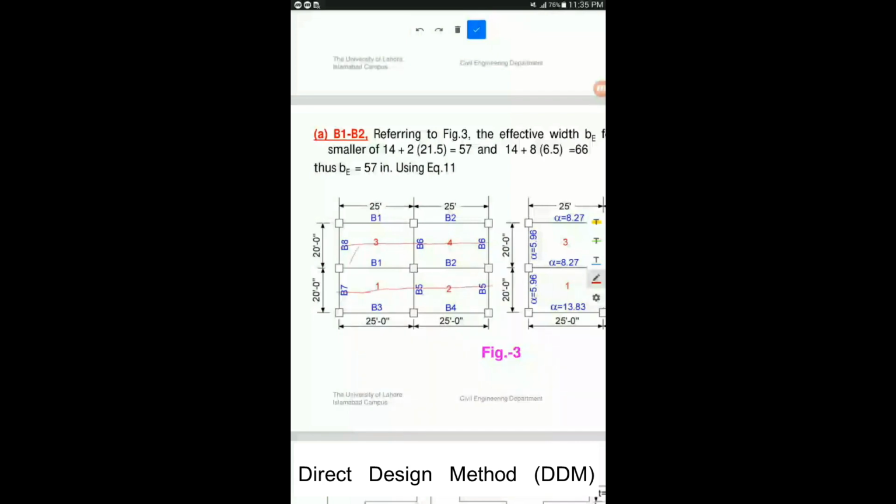This is the rigid frame A, and this one, the one hashed in a different direction, this is rigid frame B. So for rigid frame A, the width B in that formula we have discussed, IS equals BH cubed by 12, the value of B, which is the width of the slab, you can see it from here. This is the width.